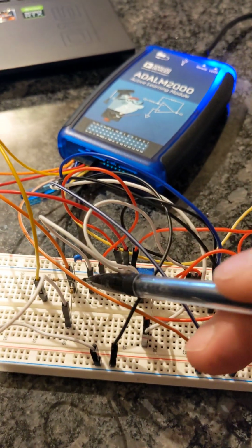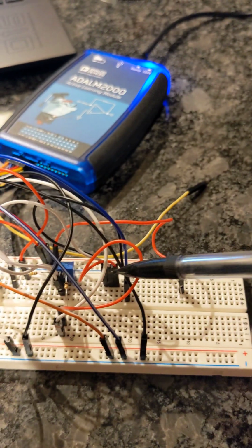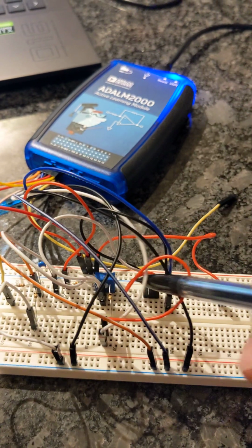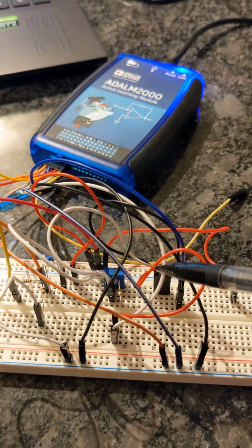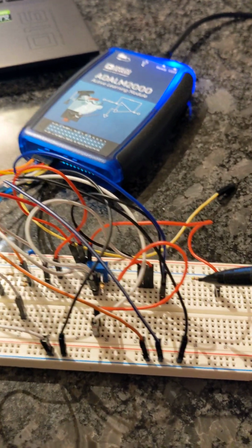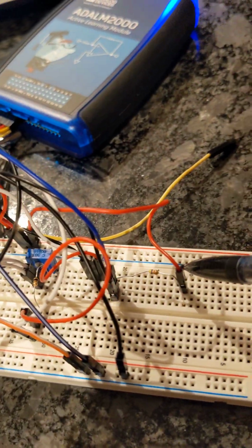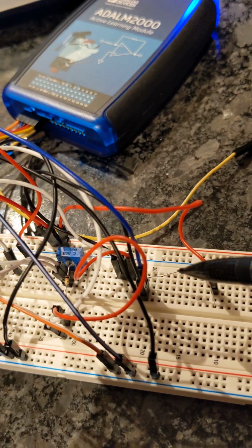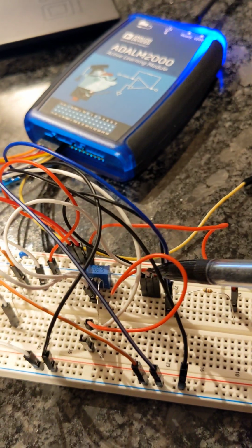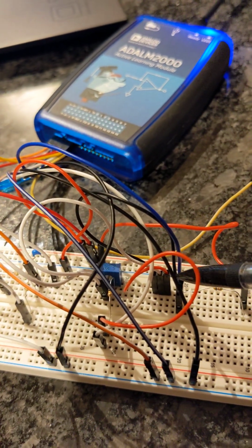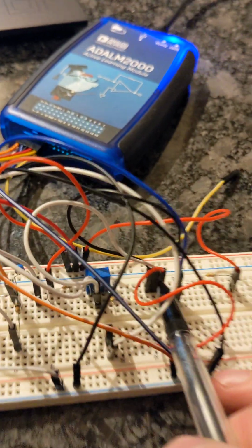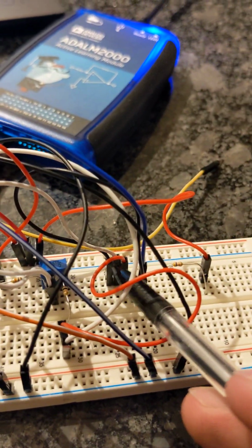Adding on to this signal, that's going to go to our CMOS. That's going to go in the gate. And then that gate voltage will then regulate the power coming through. Not power, but on this side we have our 5 volts coming through our resistive load. That resistive load is also going through the drain. The drain is on the left side here. So you can kind of see this black wire is the drain on the left side.